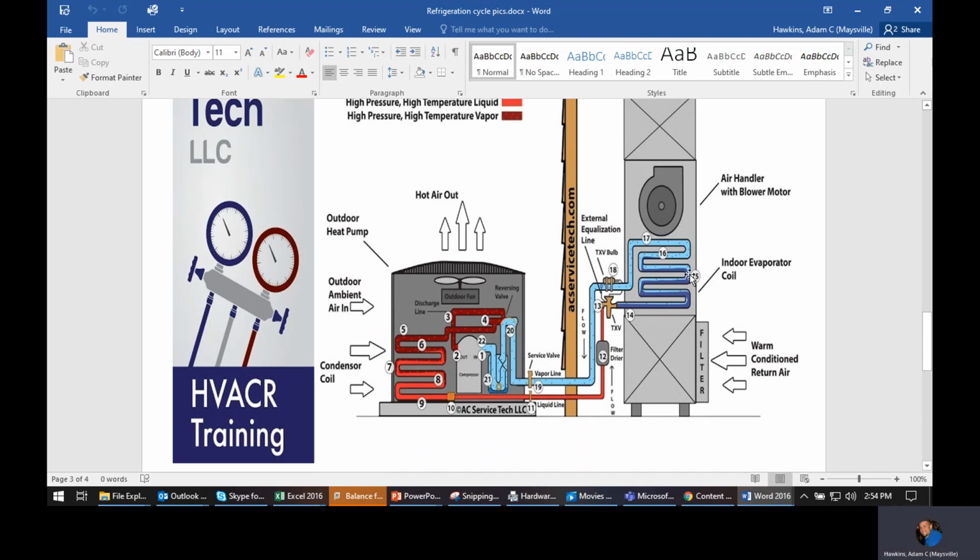That may be fine as long as it's not super hot and you're not trying to get rid of all the heat that it could be asked to get rid of, like in the middle of the summer. But once it gets hot, that's when it's going to struggle, because this evaporator is only operating at 50% capacity. Because remember that latent change is what's doing the work. So unless that thing's going through the latent change, it's really not doing anything.